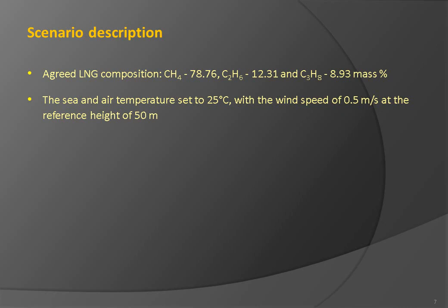Simulation of such an LNG spill scenario requires an adequate modeling description, that is, formulation in its numerical implementation of liquid layer behavior, compressible effects associated with the RPT phenomena, and dispersion of gaseous LNG in ambient air. Each section is associated with certain modeling challenges, which will be discussed in detail in two subsequent sections.